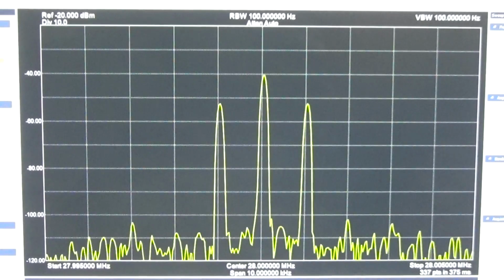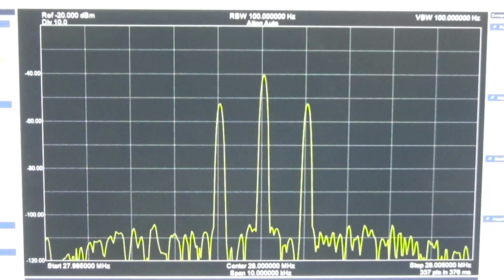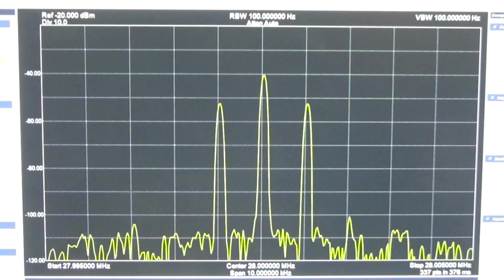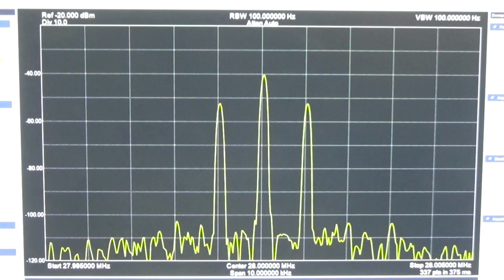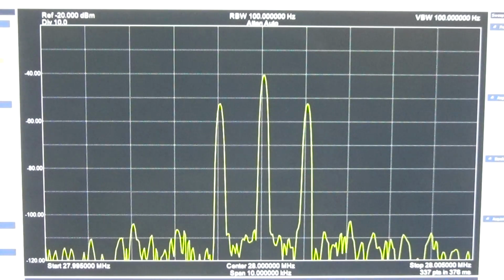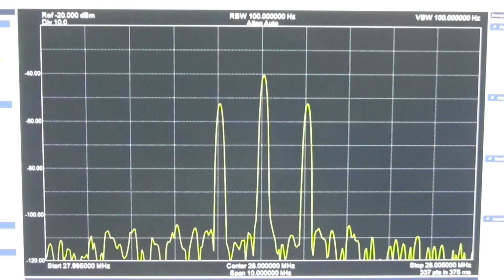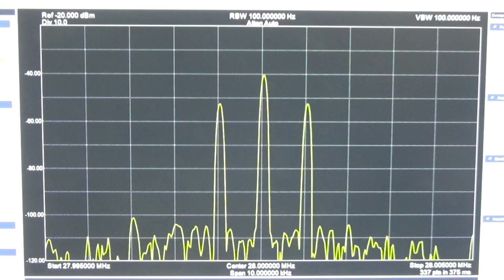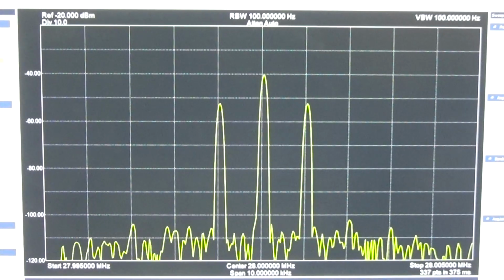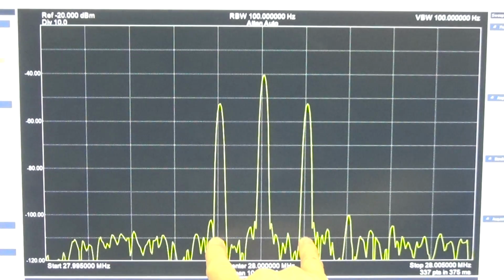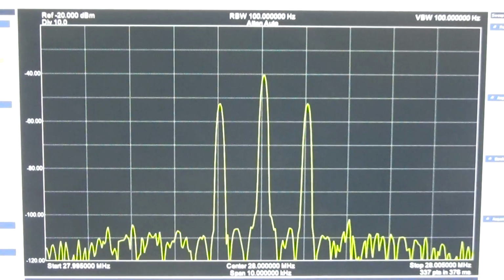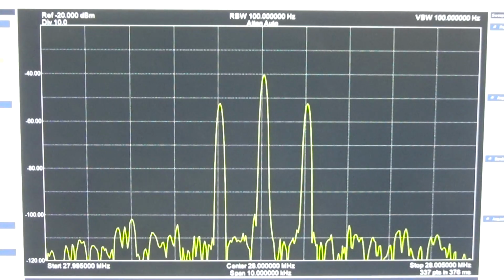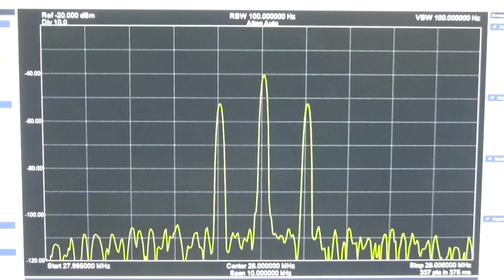Of course, a normal conversation is not only 1 kilohertz, so if we were to change to 2 kilohertz, because our speech bandwidth is of course more than 1 kilohertz, so it is 3 kilohertz or whatever. So it is of course more than this 2 kilohertz. But you clearly see that the bandwidth of an AM modulated signal is narrower than an FM signal.